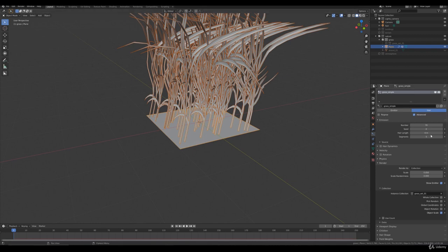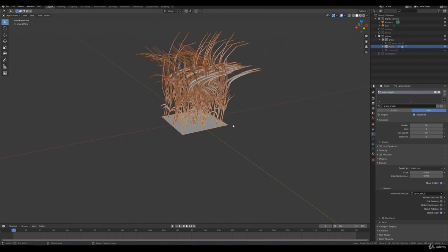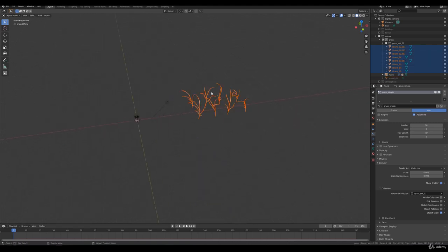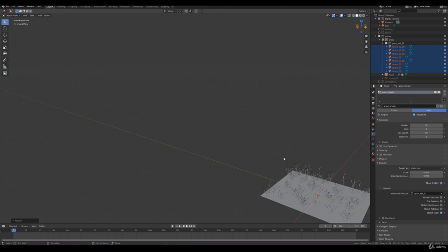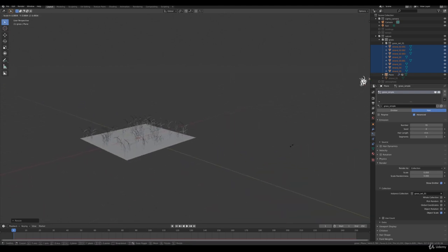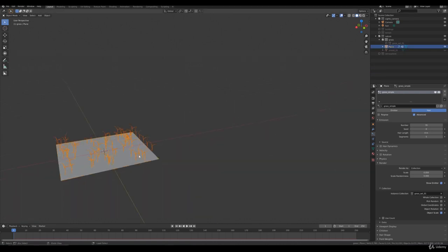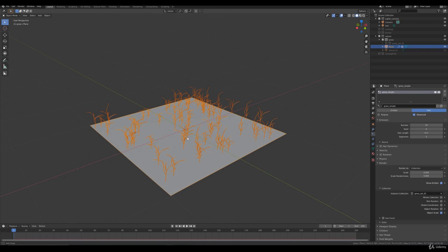So there's a solution of scaling, but these strands are so big, I like to scale them by the source. So let's grab them and scale them in object mode. Not many times we scale in object mode, but these we want to scale in object mode. So go to the plane. Yeah, just a bit more. All right. So disable the grass_set_1 because we don't want it to be visible. Ctrl+Numpad period, so we have the plane in the middle.